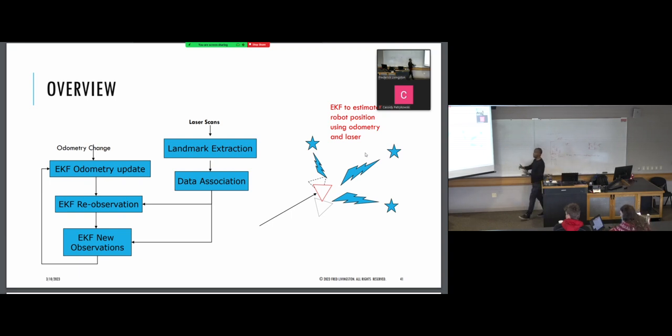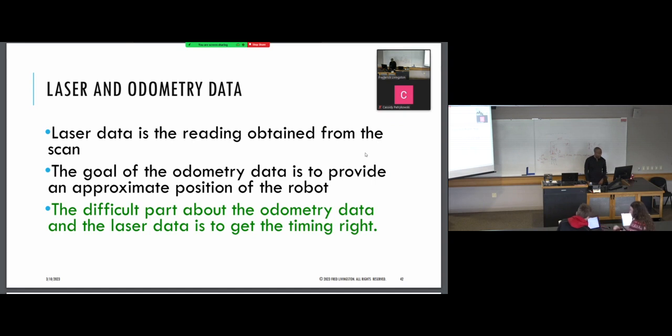I'm going to compute my position and my orientation from those two data, and I'm going to use an extended Kalman filter to estimate my actual real position. That real position is an estimate of where I think I'm at on the track, or where I'm at in the room. So I think I'm at this XYZ location on the track. And that's pretty much it. That is SLAM in a very simplified manner.